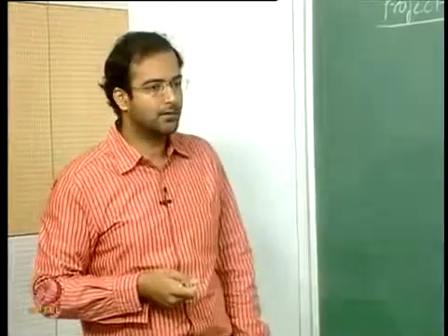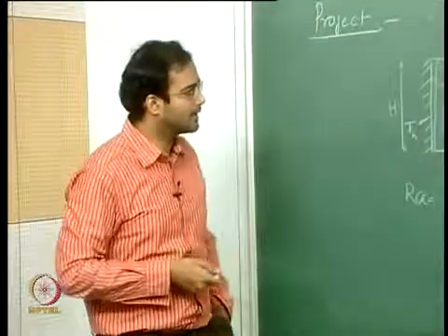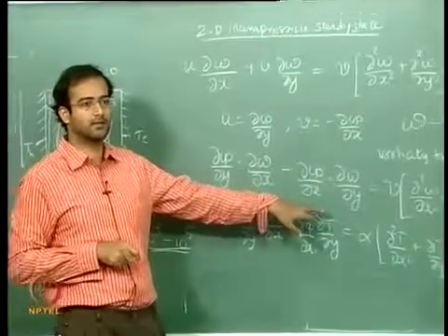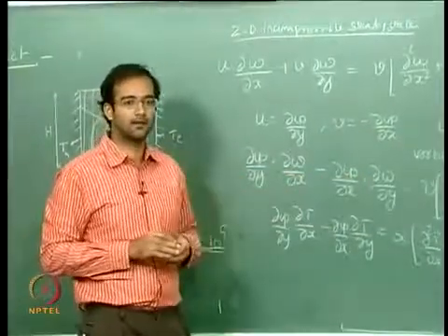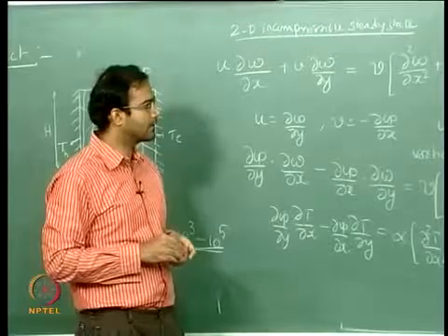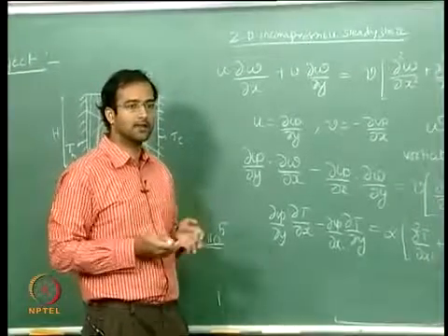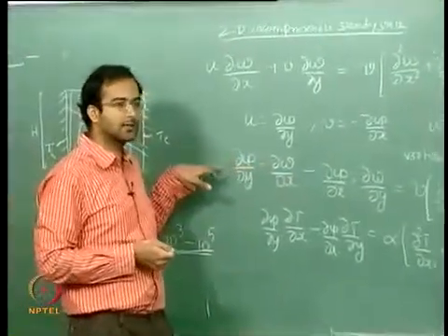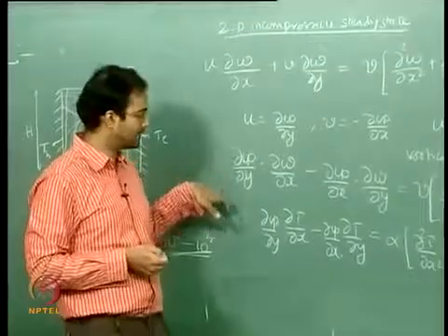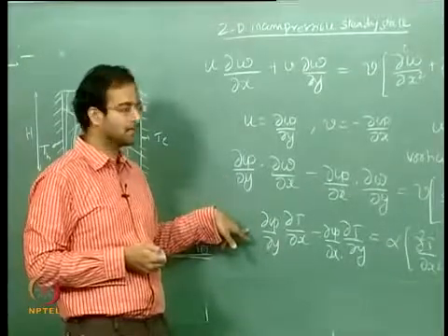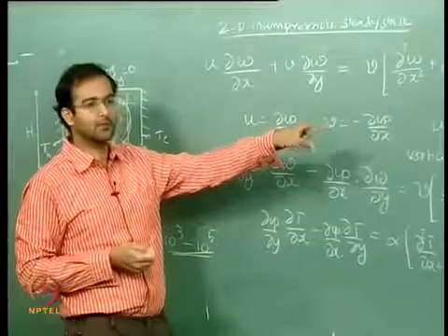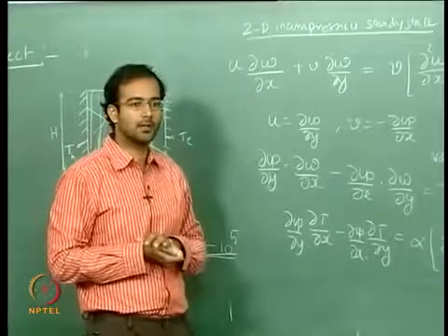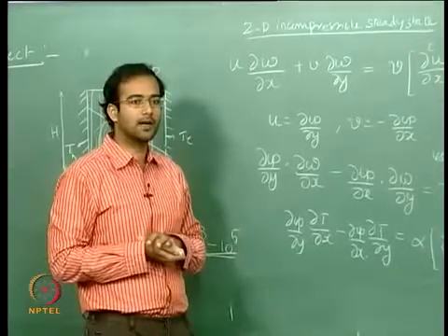So you can have a look at the document I have posted, and that clearly gives you how to write the finite difference expression for each of the derivatives, the first order derivative, the second order derivative, and so on, and you solve these equations together iteratively, okay. So solution for omega requires of course the knowledge of stream function as well as the temperature. Solution for temperature requires the knowledge of stream function. Solution for stream function requires the knowledge of vorticity. So all these 3 equations have to be solved simultaneously, but it can be solved iteratively, okay.